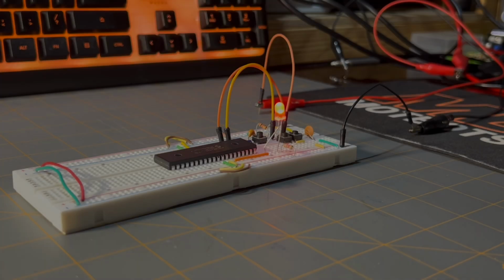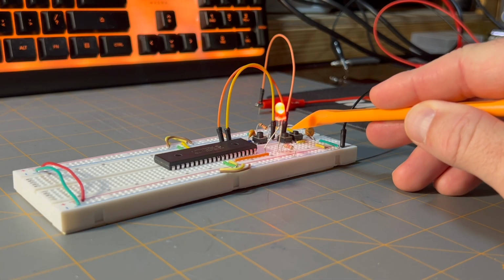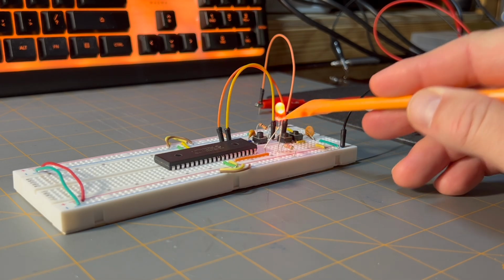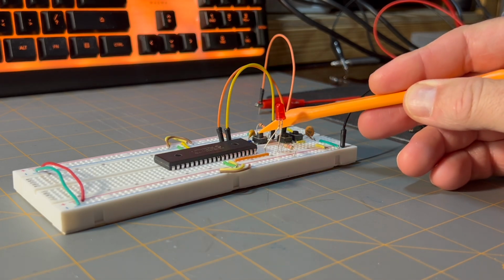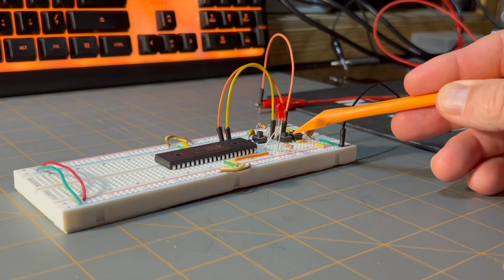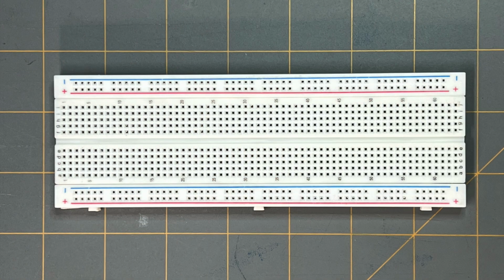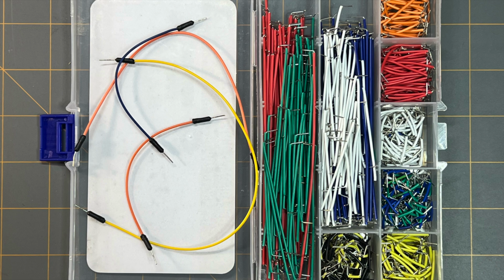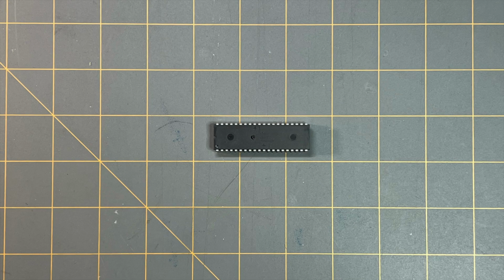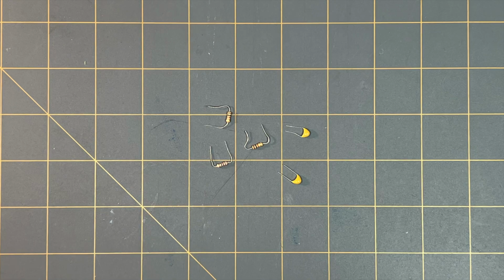For this project, I've programmed the PIC 18F4525 microcontroller to wait for a user to press either of the 2 switches that will control whether a red LED is to be turned on or to be turned off. The circuit uses very few components to accomplish this task. All we need is a breadboard, some jumper wires of varying colors and sizes, a PIC 18F4525 microcontroller, a few momentary push-button switches, a red LED, a few resistors, and a capacitor.